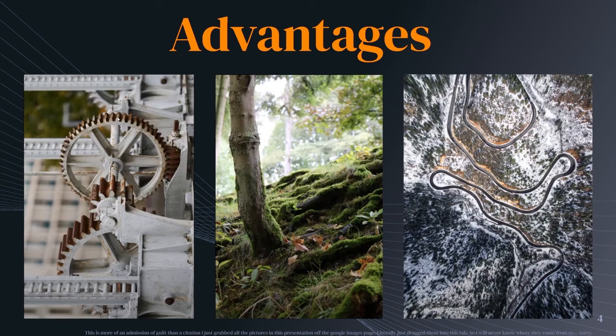Later, if the person using it wants to change it from this big gear to this small gear, all they have to do is shrink your starting circle and lower the amount of segments so that you have fewer teeth. It would be a really easy conversion, and you can do it for all these repeating parts too.